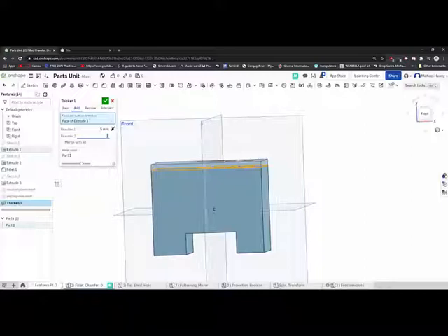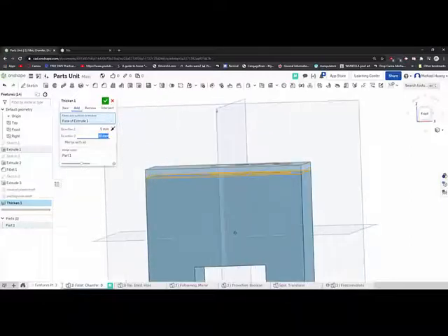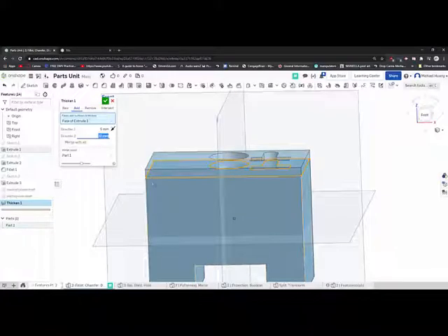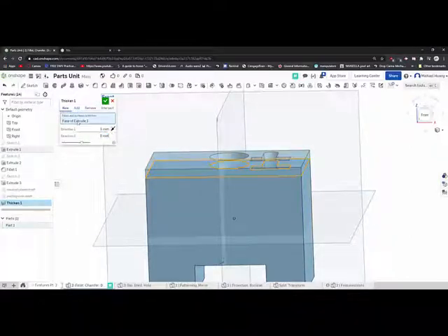And you can actually thicken both ways. So you'll see it's 10 millimeters down, but in this case, the material it adds is taken up by the part already, so it doesn't really show. All right, just like with your extrudes, you can click new and create a new part, right, from your thickened material, or you can just add it to an existing part.